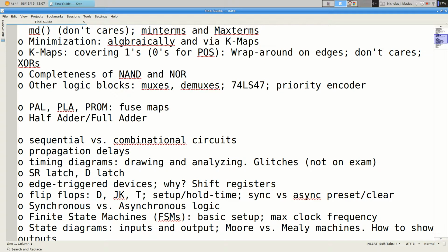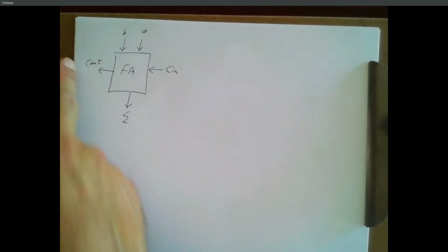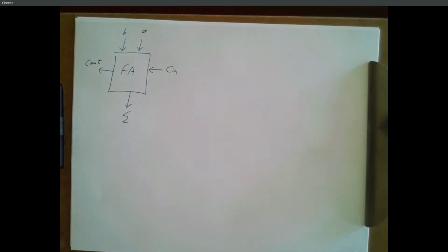And you've done homework questions on this. You had a few different versions of lab experiments related to this. So just make sure you're comfortable with the truth table, how you would implement that. There you go, full adder. So carry in, carry out, lay them out side by side, carry out from here feeds the carry in on the next one, and so on. What's the output on the bottom? That's just a sum. Oh, okay.